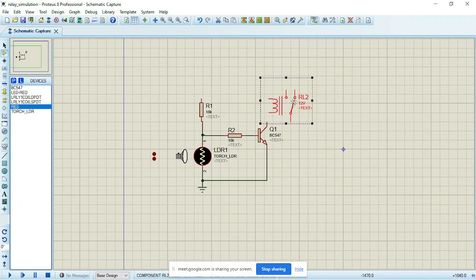That's why we are including this transistor. And again, we need to send a signal. Let's say you are using a microcontroller, you cannot connect the signal from the microcontroller directly to your relay. So you have to attach a transistor to also amplify the current that will enter the coil. So you connect your relay here.